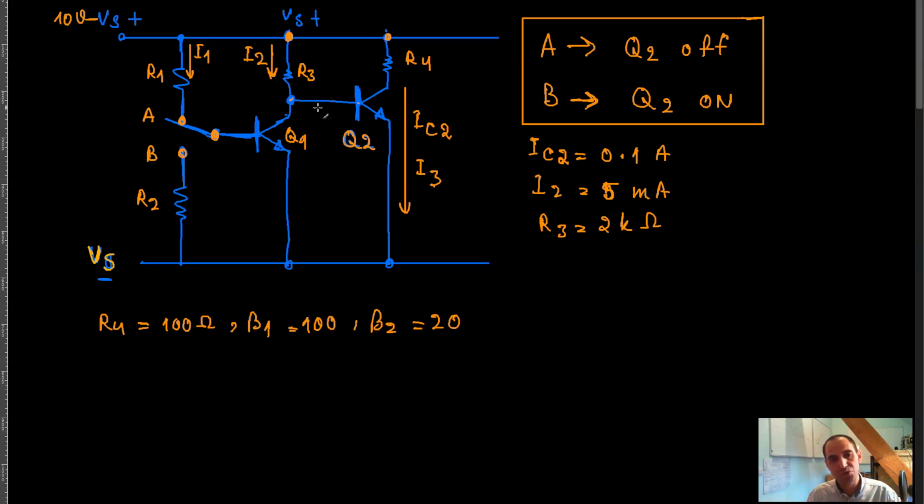When it's turned off, it's not important, of course, and you don't have to worry about that. When it's turned off, it's essentially tied to the ground. When it's turned on, then the current over here has to be 5 milliamp. That means that this current becomes the collector current of this transistor, right? And we have already found the collector resistor. We have already found that, right?